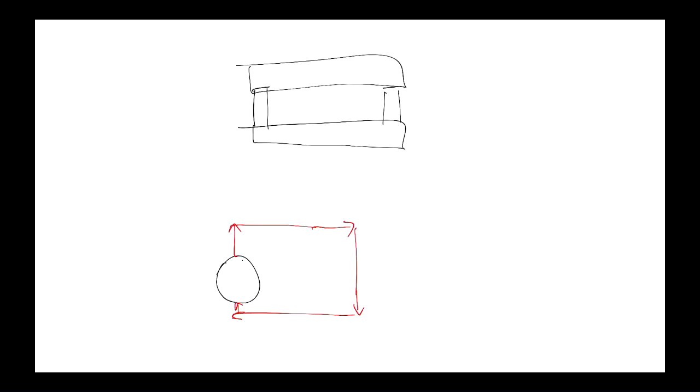And so your goal this week in the workshops is to modify the state machine that controls the robot, that only has two states. If you think about the robot's motion, it can only be going forwards or turning, into a state machine that can describe the behaviour of avoiding an obstacle.